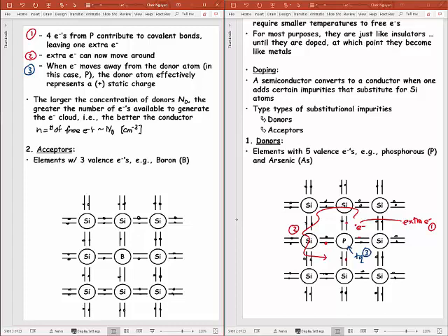Well, that goes into material that this class won't cover. That will be in EE143. Maybe EE130 talks about that as well, but 143 is where you actually get to do it in the lab. And you'll see that it takes high temperature processes or some kind of high energy process to just throw that phosphorus into the silicon. So you can just bombard the silicon with phosphorus. If it's high enough energy, phosphorus gets in the silicon. You then heat it to repair damage, but you end up with phosphorus in the silicon and a lot of electrons to move around, and you've created something just like a conductor.